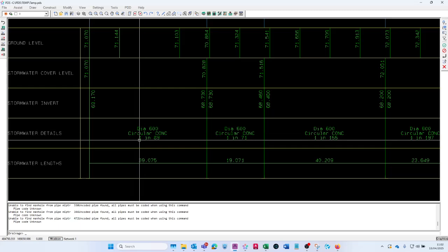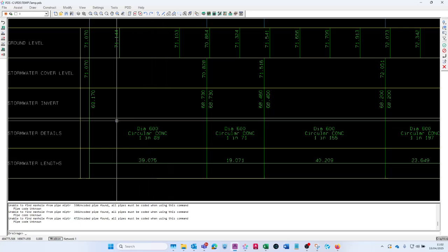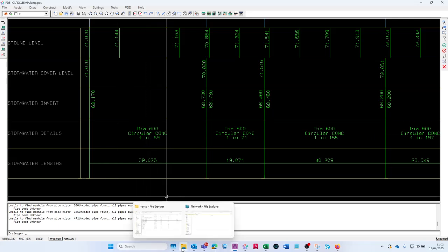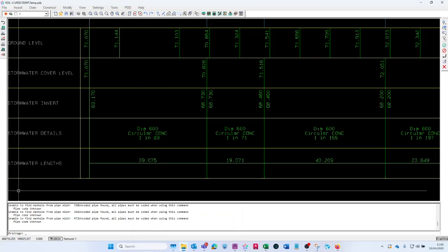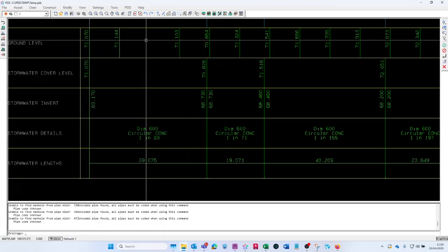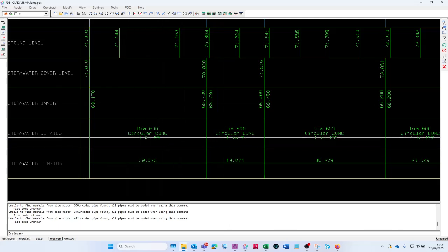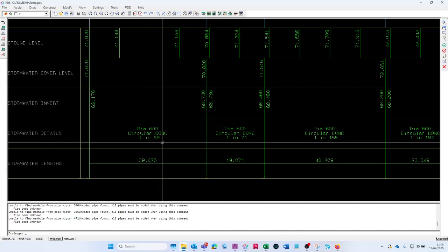This will say either circular or rectangle, and that comes from flow, based on the pipe shape. The materials are based on the data file, or your parameter file, sorry, this file here. It'll give a pipe material based on the size, so you can edit that, and you can edit the displays to create your custom one, so that isn't shown. I must admit I don't bother. I just simply delete off the material type in CAD. I just find it easier that way.